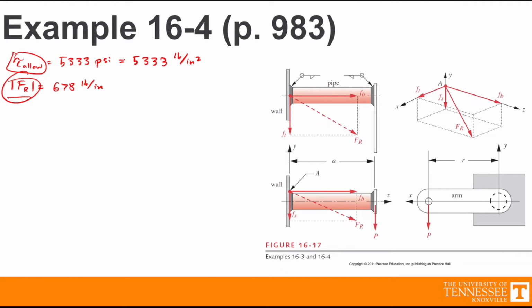And if you'll remember back from the initial stuff when we were talking about the geometry of welds themselves, the driving dimension on welds is the throat length, which, if we're looking at a complete penetration groove joint, the throat dimension is here. That's basically the thickness of the plates. And if we're looking at a fillet weld, so between two things here, here's our weld, your throat is this dimension right here. So this is what we're looking for.